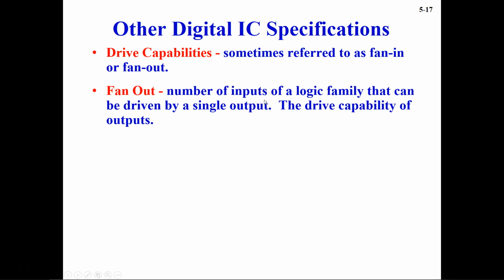So in other words, we can say that if the fan out of a standard TTL gate is, for example, 10, then it means that the output of a single gate can drive up to 10 inputs of the gates in the same subfamily. So typically the fan out value for standard TTL ICs, if you search, you will find it to be 10,